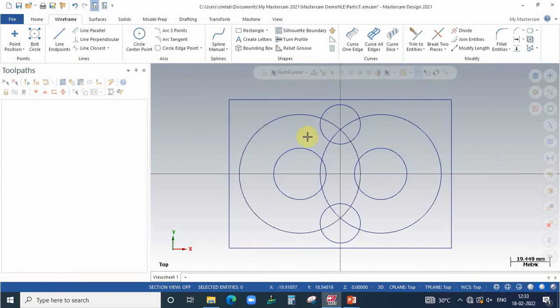The next step will be creation of slanting lines. From this center point to this center point of the circle, we need to create a slanting line. For that, we have to select the line command. Before that, if you keep the mouse, the center point will not be visible. If we get the center point exactly, we can directly connect the 2 points.